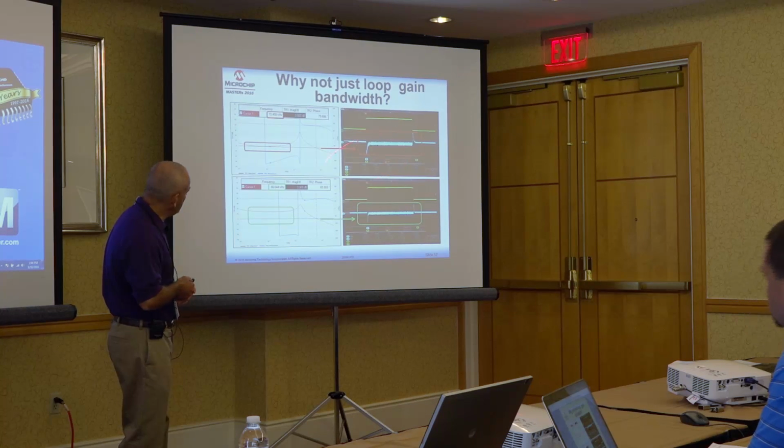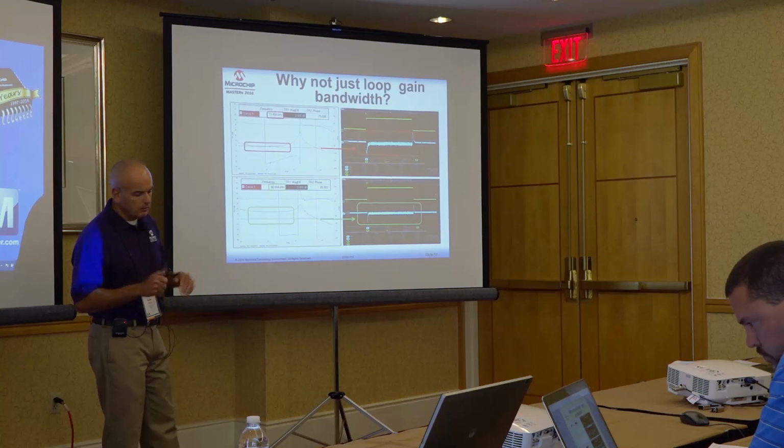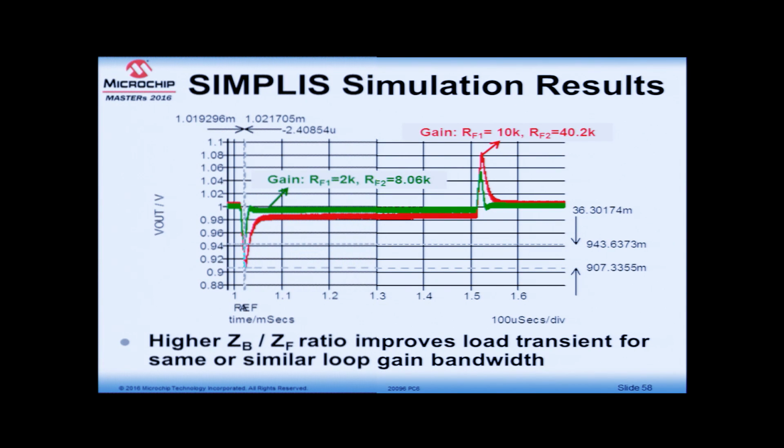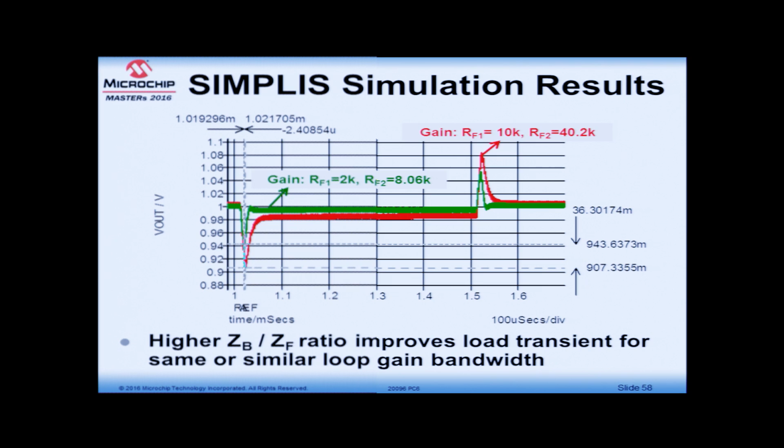Here in this measurement, our output voltage setting, you may not see it, but was around 3.3 volt. Now what happens in simulation with the output voltage setting around 1 volt. Here we keep the ripple injection impedance the same, and we are changing the impedance level of the feedback impedance. We see that in the case of a higher impedance level, we have the red curve.